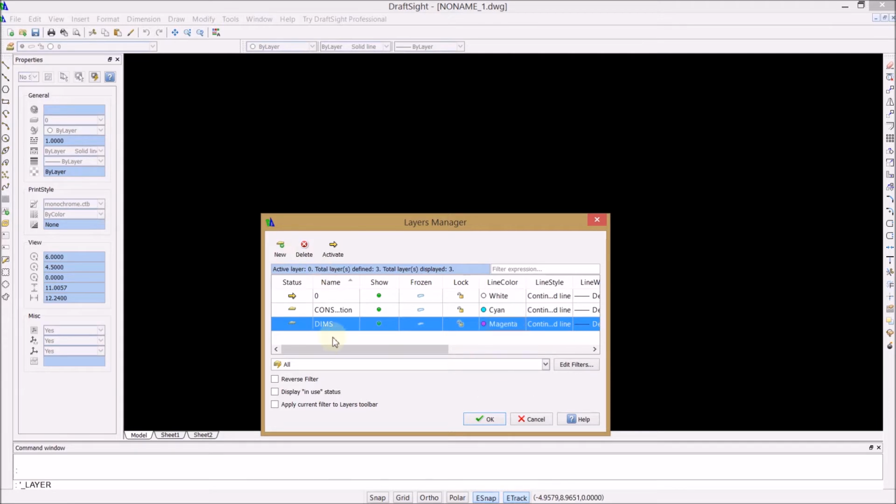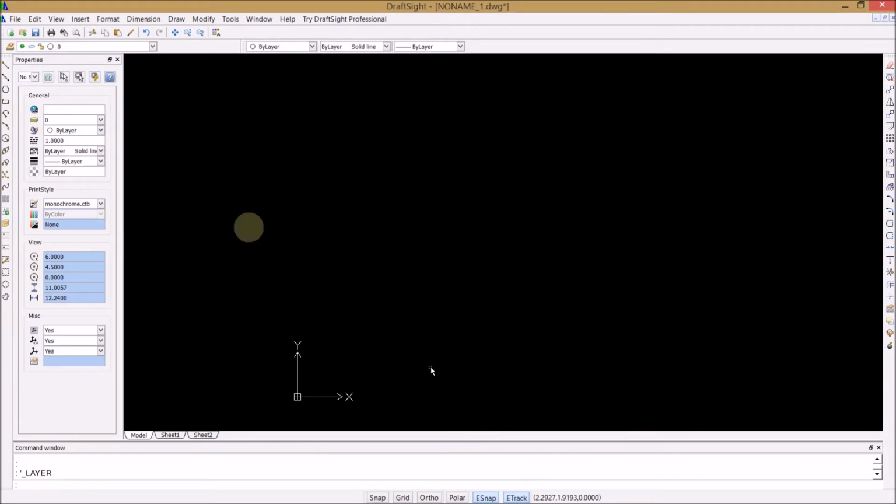I've also switched my background around so that it's black, just because I can see lines easier on a black background. Now, up here in the left corner, there's a drop down. You can select what layer you're drawing on and switch that as you go along. Mostly what I use is the line command, rectangle, the arc, and the circle. You can use a block, like a combine or attach command, to put a drawing piece all together so you can move it without having to grab a lasso around it.